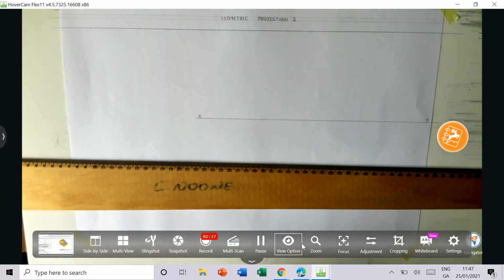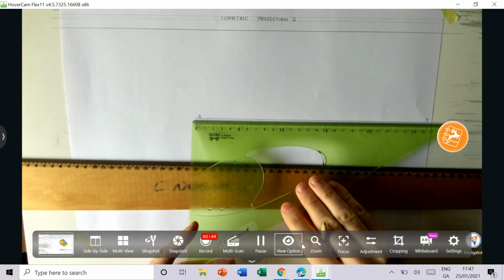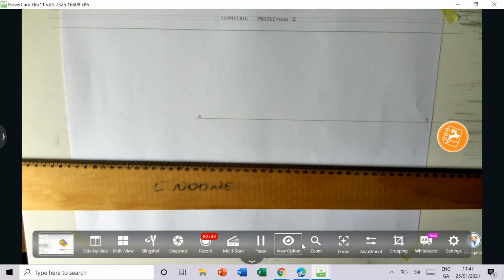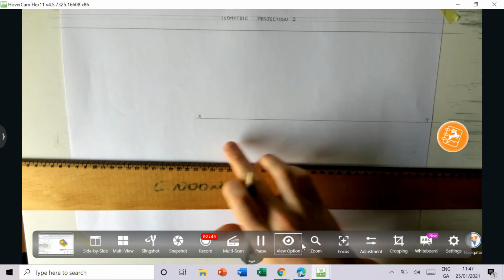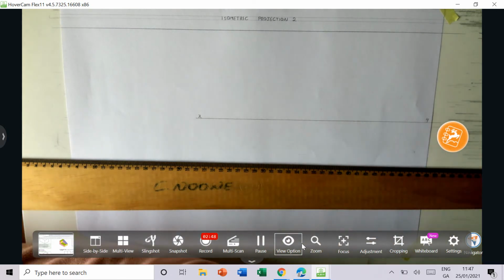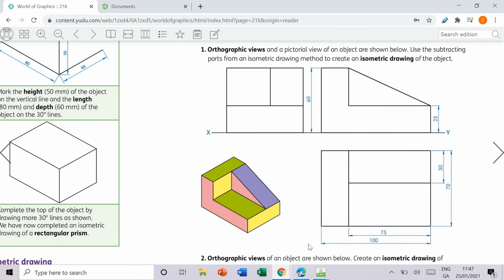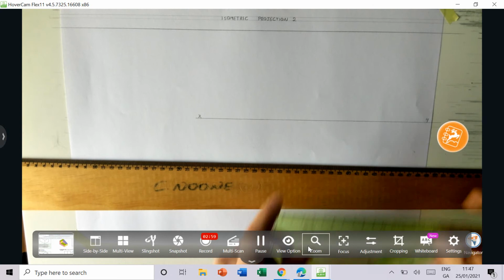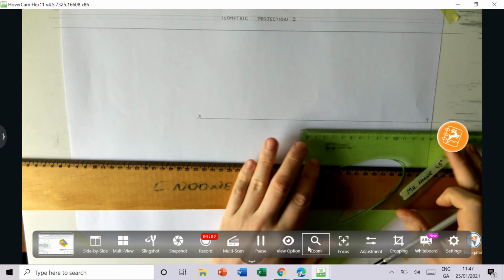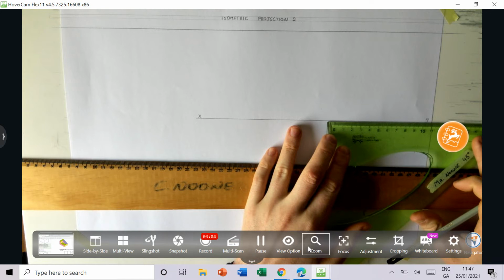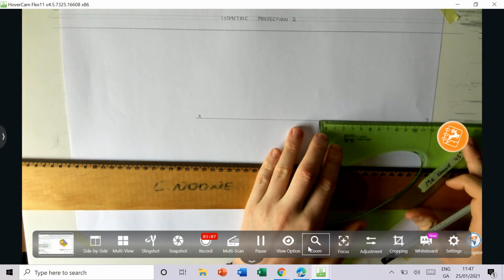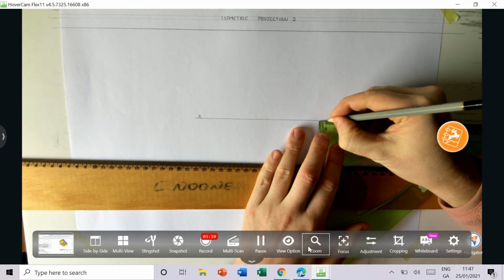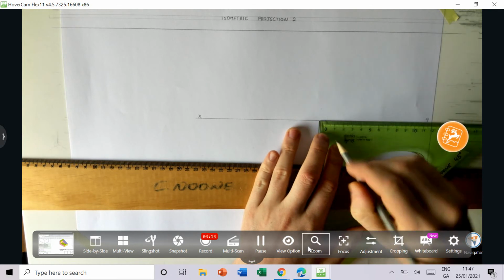So I've come down 100, and the length of that line, just to give you an idea of how long that is, is 270 millimeters. Now, what I just said there was that the height is 60 and the width is 100. Okay, so let's draw that in. From the edge of my page now, I'm measuring in 120 mil. That's going to get me this point.